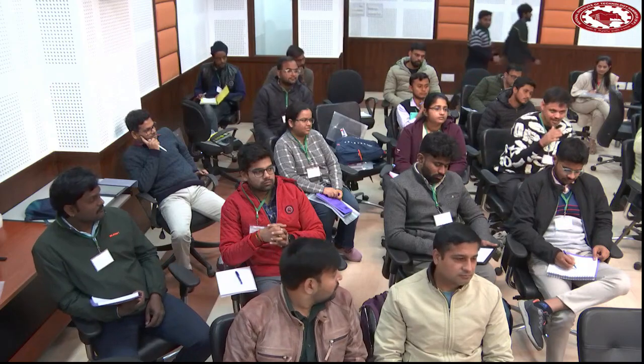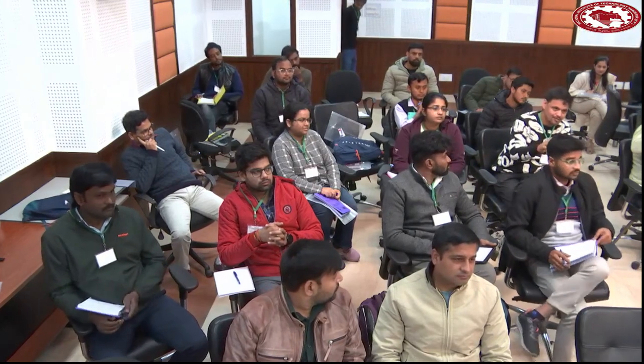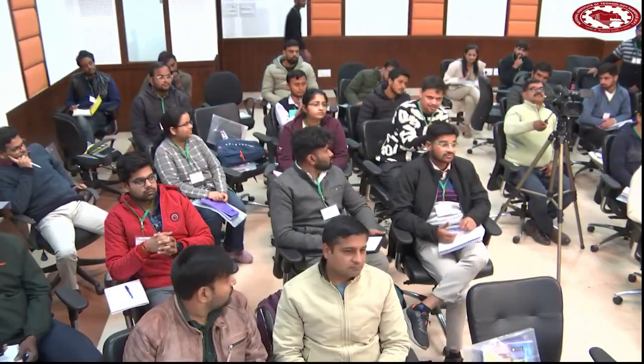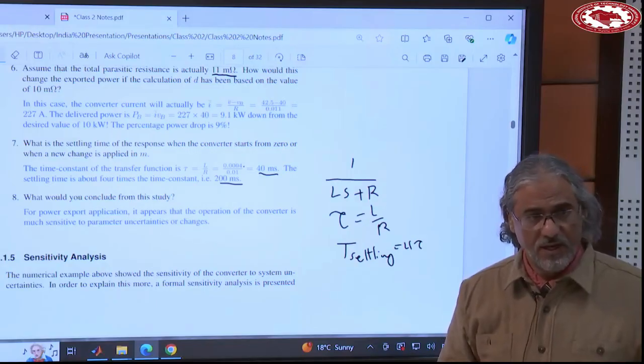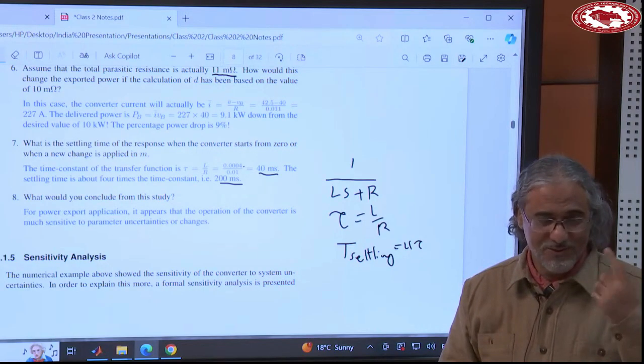My question, I'm thinking that will be covered in the second lecture by you only. But in two-stage converters, when it comes to solar application, the DC-DC converter and the DC to AC converter, who will take care of maintaining that DC link at a certain level? Whether it's the DC-DC converter from the solar side, or the inverter from the grid side? In the PV application, it's the inverter. Right, because the first one takes the responsibility for controlling the PV voltage. And we said it can only control one. It cannot control more than one.